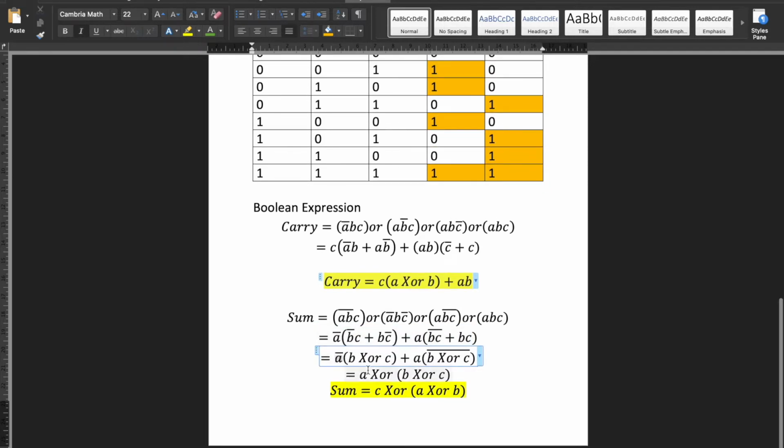Okay, now we can move on. So this stays the same. Not A stays the same, and this part here, as I've mentioned above, can be converted to B XOR C. And this part here, since you already know that this part can be converted to B XOR C, then this is basically the opposite of that. So we can say B XOR C with a bar at the top that says it's not. In spoken language, we can say B XOR nor C.